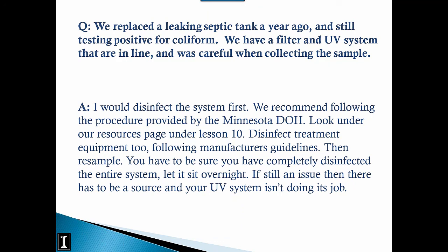And what we tell folks who run into a situation where no matter how many times they disinfect, they still have coliform coming back time and time again, you really only have two choices. You can either drill a different well somewhere that's further away or away from everything, and you're assuming then it would be safe and not contaminated, or you can add a continuous system. And that's why this one is such a unique problem, because what we'd recommend is either adding continuous chlorine or UV in order to kill any bacteria that might be coming into your home.